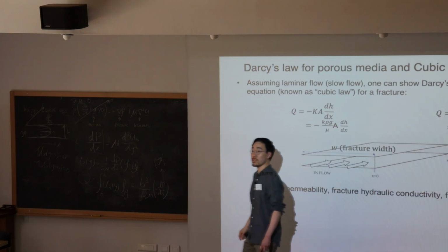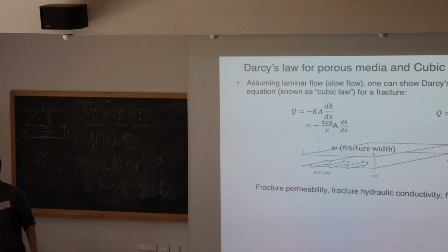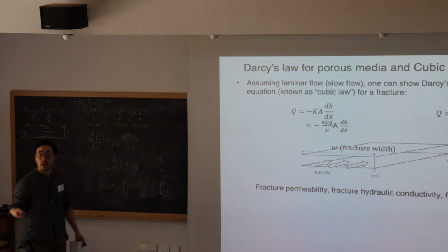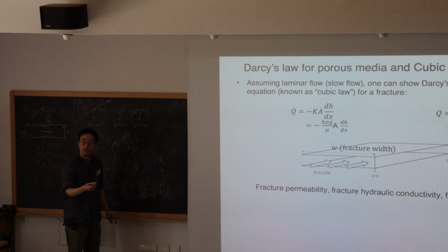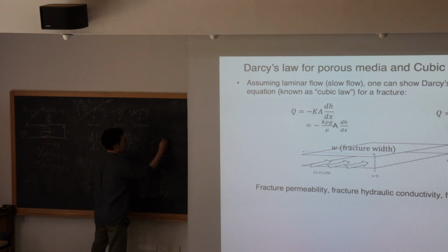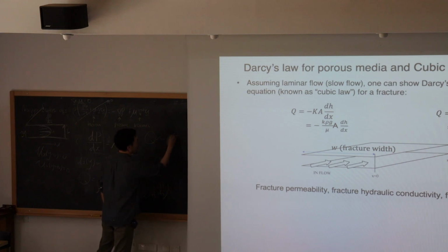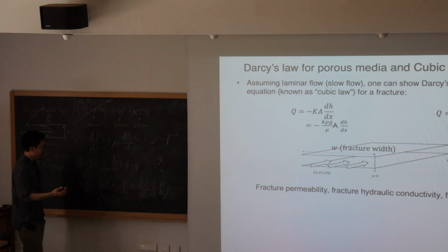Any question? Yeah? What if you have a tube instead of a plate? Yeah, of course there's an analytical solution, and that's the R to the 4 relationship with Q. Is it correct, Richard? You can do the exact same algebra, and then it goes Q proportional to R to the 4. In the radial coordinate, you can do the same mechanics.